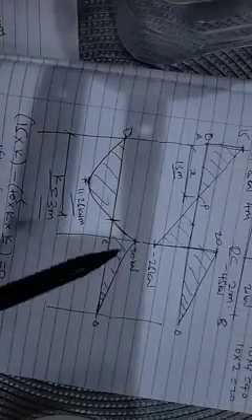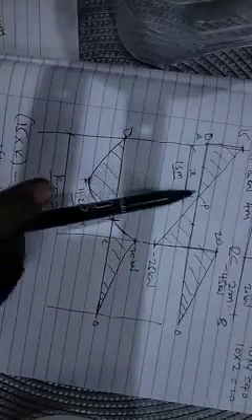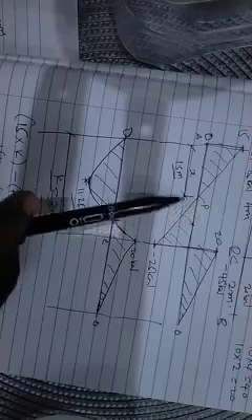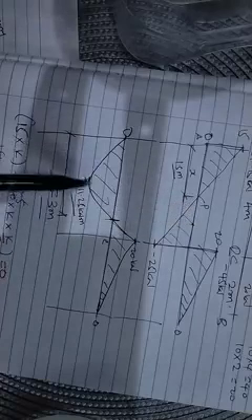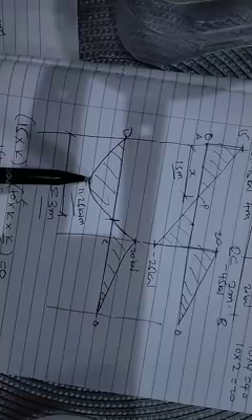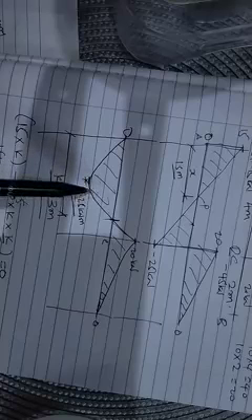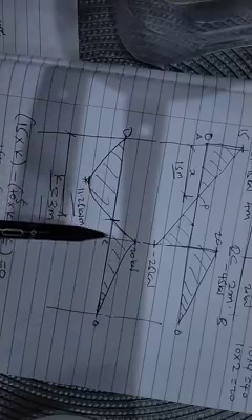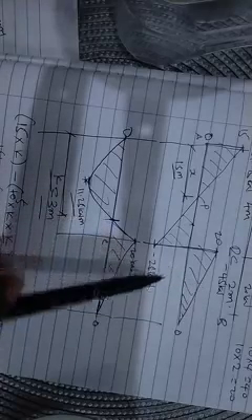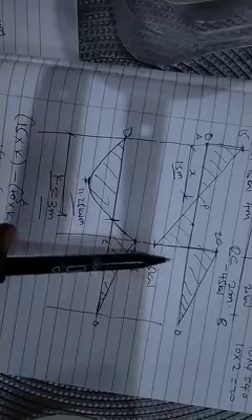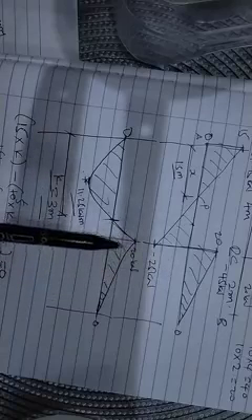So I think from here you can make some few observations: where the shear force is 0, we have the maximum bending moment. And then at this point of support is whereby we are getting the design shear force and the design moment.